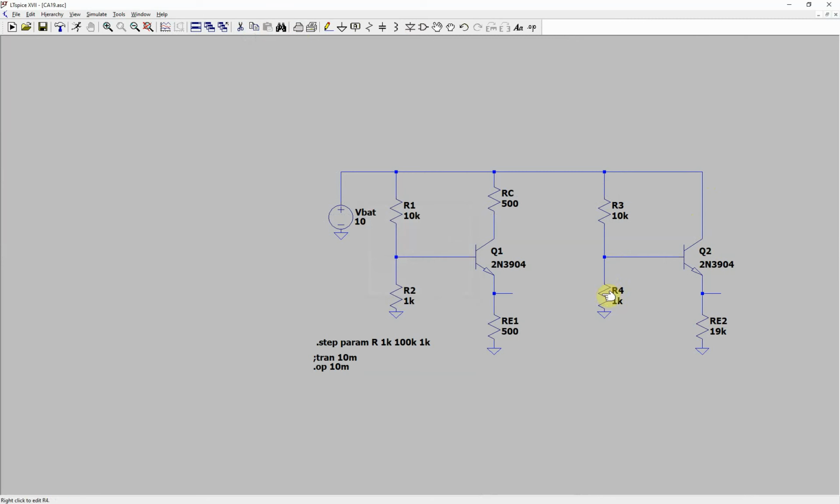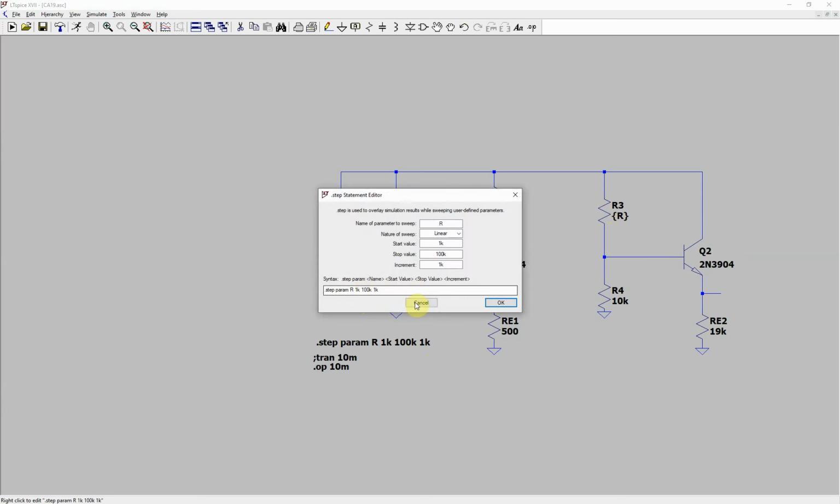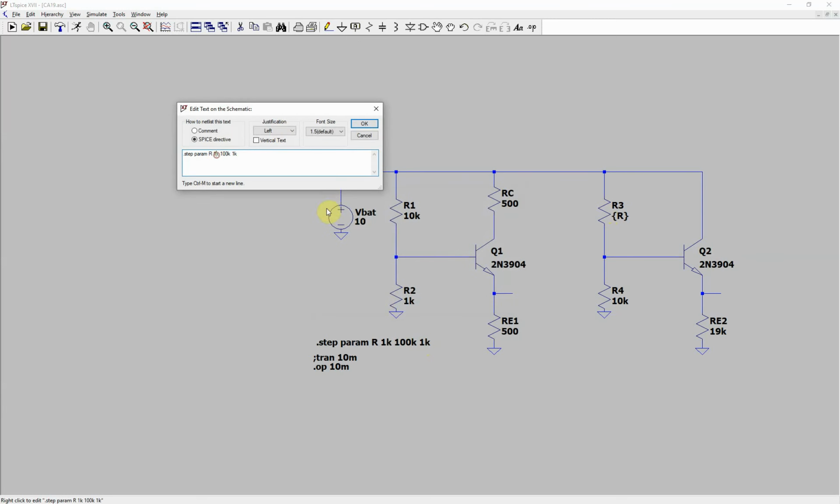We're going to want these bigger. We want these to be a lot bigger than the 500 ohms because we don't want loading between these two. So let's start with, this is 500 ohms, so let's do 10 kilo ohms. And in this case, we want this to be at least 10 kilo ohms.